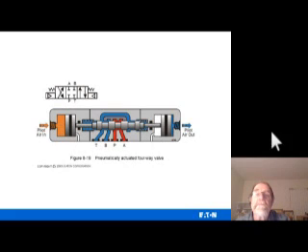Okay. Once both solenoids are de-energized, the springs will center it, put it back to the center. If this solenoid energizes and moves it to the right, and then another operation comes along, it de-energizes this and then energizes the solenoid here. PLCs are usually programmed to do this type of control of this type of device.